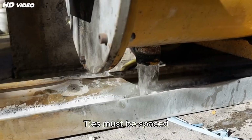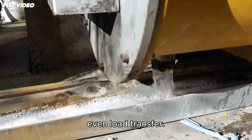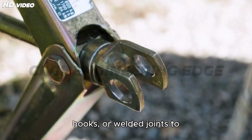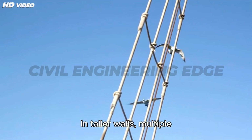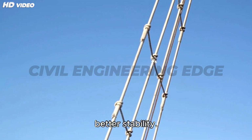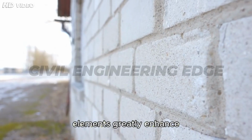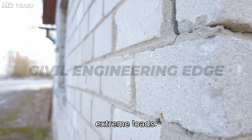Ties must be spaced adequately to control crack width and ensure even load transfer. Additionally, ties must be properly detailed at junctions with bends, hooks, or welded joints to resist pull-out forces. In taller walls, multiple layers of ties may be used at varying heights for better stability. These small but critical elements greatly enhance the wall's durability and performance under extreme loads.